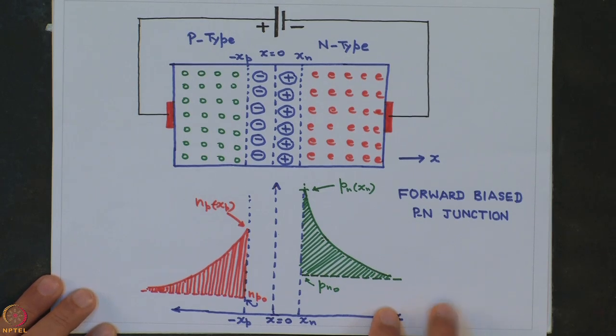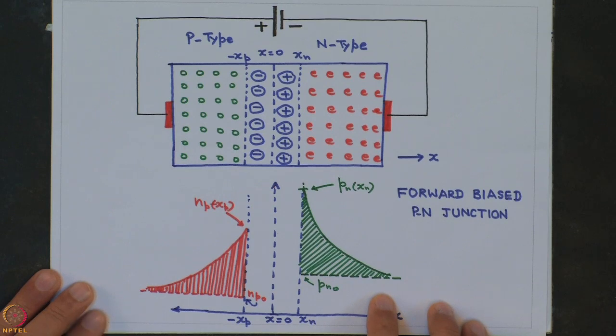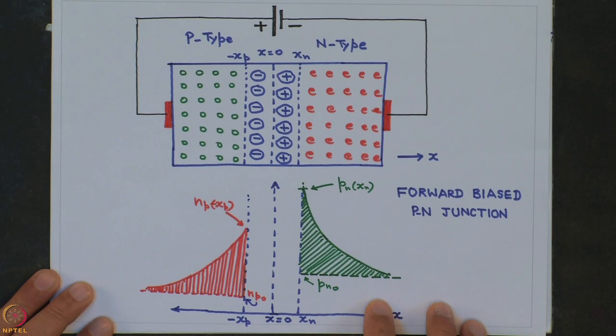As they flow from left to the right, they are actually neutralized by electrons. To maintain this equilibrium profile, which you can see here in the green color, electrons are replenished by the source negative terminal, and there is no problem with it because there is no dearth of electrons now. So there is no dearth of the supply of the charge carriers to compensate this.